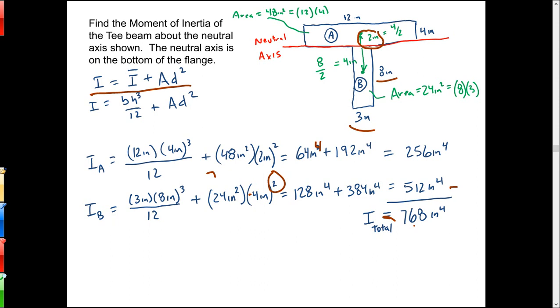What we would do then, and this isn't on a given page, I just made this one up, and we went through it at the end of class last time. So what we're doing here is finding the moment of inertia about what I'm calling the neutral axis, which on this one just happens to run at the base of the two rectangles. But I decided I'd use the transfer axis theorem on this because it's more general. I just wanted to demonstrate that.